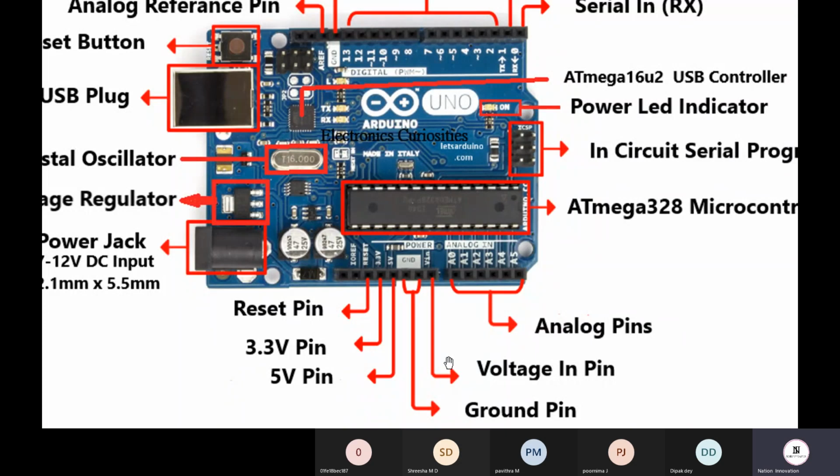Make sure of this consideration whenever you provide a supply to the Arduino with this Vin pin: it is supposed to take the input supply from an external device. It can be a battery source, it can be a direct DC plug as well. So the thing we have to make sure is to never ever cross a 9 volt supply for this pin.